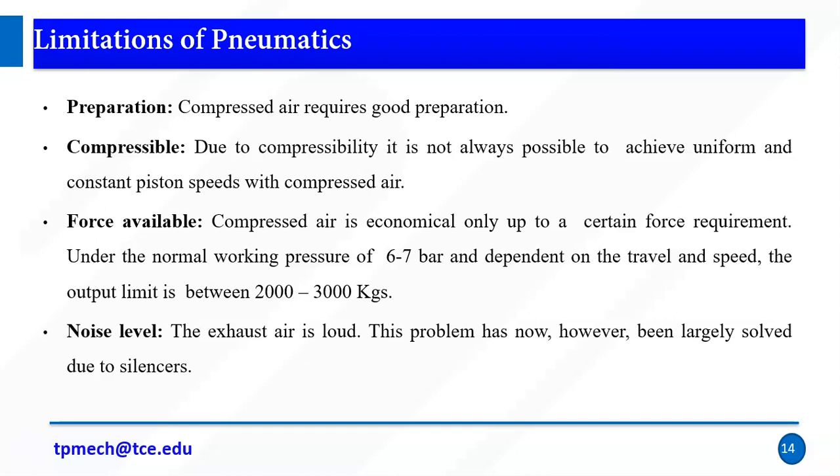The second one is compressibility. This is one of the major disadvantages or limitations. Due to compressibility, it is not always possible to achieve uniform and constant piston speed with compressed air. So, for example, if you want to lift your bike or your car, we never use pneumatics because the weight of the vehicle will affect the air. If you use pneumatics, due to the compressibility factor, it cannot move, right? In that case we use incompressible fluids.